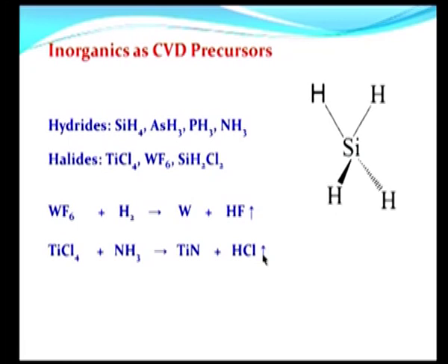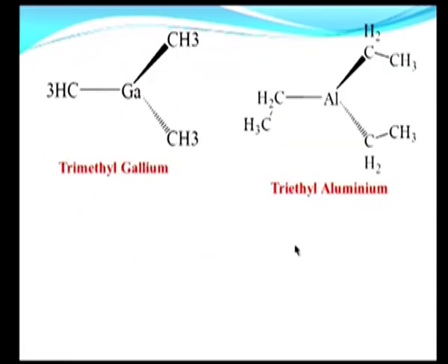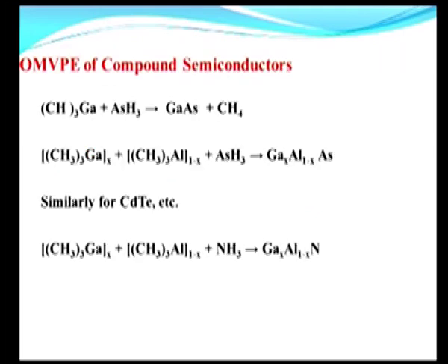materials for CVD. So, these are all different precursors, and one of the things I mentioned is the formation of gallium aluminum arsenide, usually in epitaxial structures of nanometric dimensions, that is just obtained by having an appropriate proportion of the gallium precursor, which is trimethyl gallium, aluminum precursor, which is trimethyl aluminum, and then having the reaction with arsine at about 600 to 700 degrees to give us gallium aluminum arsenide of the chosen or desired composition.